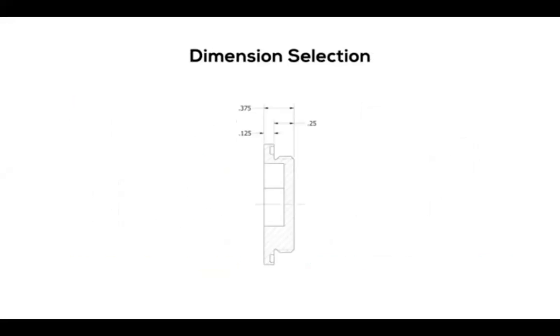You cannot have multiple dimensions that conflict with each other. For example, this view of the bore cap has an overall length dimension, as well as these dimensions that define the thread length and flange thickness. These dimensions conflict, and one of the 3 is redundant. To minimize the tolerance stack, it's best to dimension it with these 2, but having the overall length is helpful, and we want to show it on the drawing.